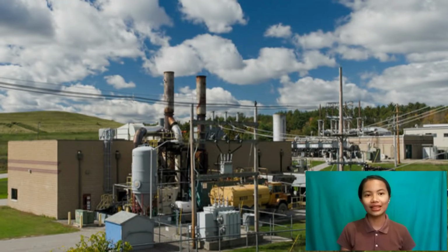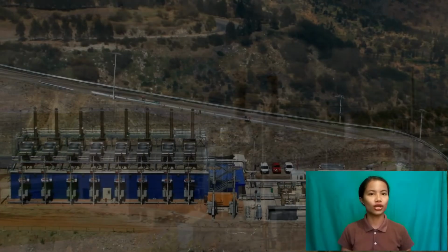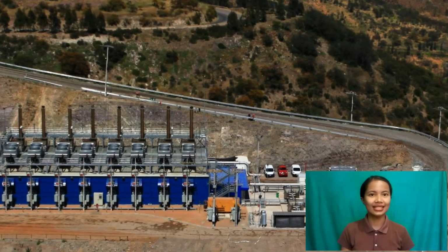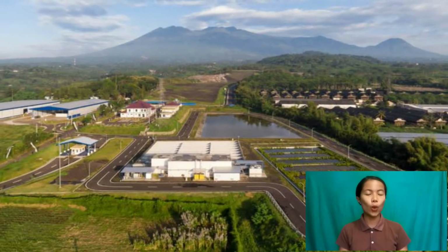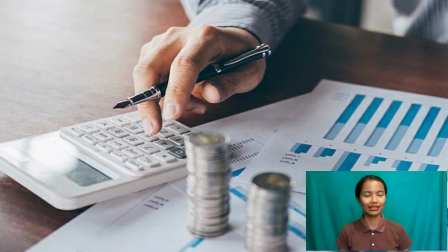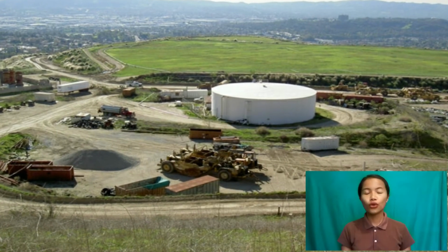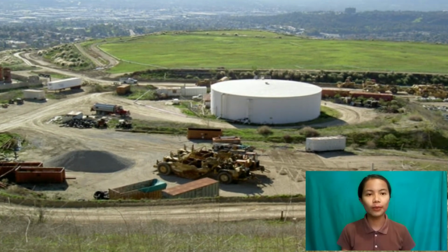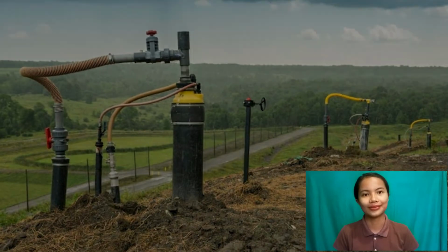The sanitary landfill design also includes structures or equipment for controlling water pollution and the movement of decomposition gas, including a recommendation of the specific use of the site after landfilling is completed. Finally, determining capital cost and projected operating expenditure for the estimated life of the project. These include parameters such as volume requirements, site improvement, control of surface water, groundwater protection, gas movement control, sanitary landfilling methods, and lastly, summary of design considerations.